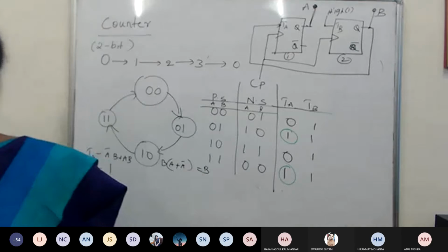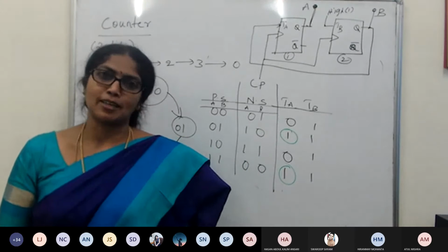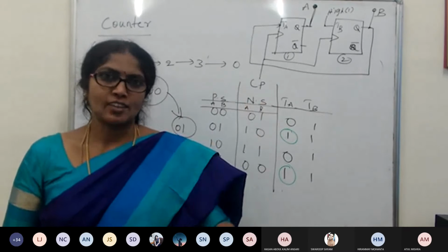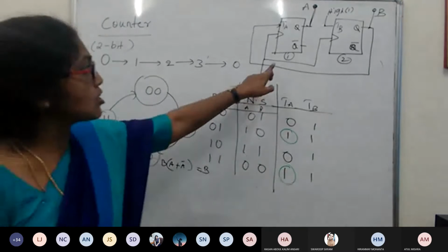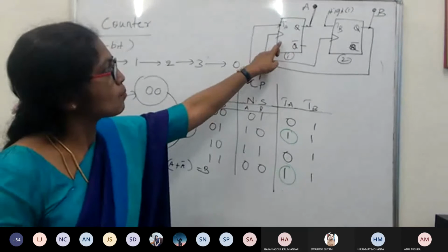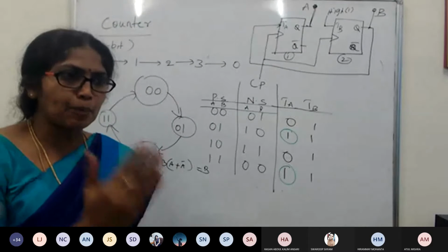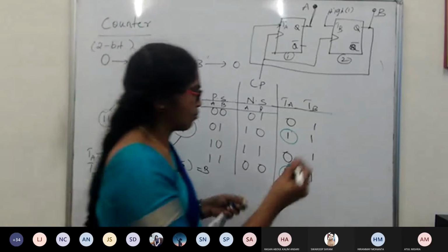But we have another option in the flip-flop, which we use practically. We can have a preset. We can predetermine it and preset the output. That option is there. Practically when we do it, we can work it out. Because I am showing the logic diagram only with clock pulse and T. But in fact, if you flip through the pages of your digital textbook, you will have 2 more pins.